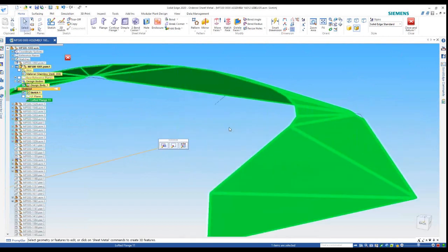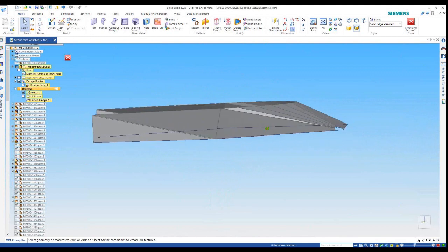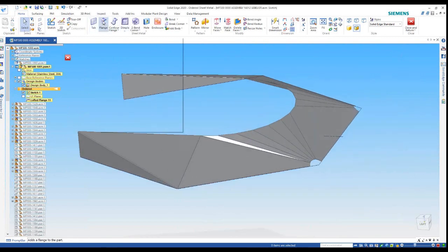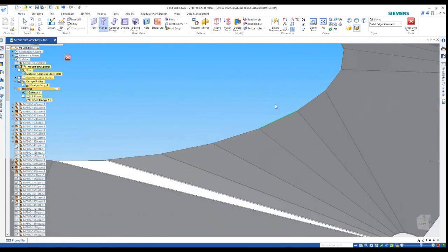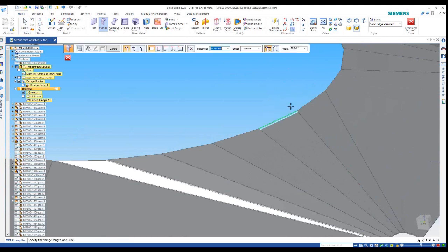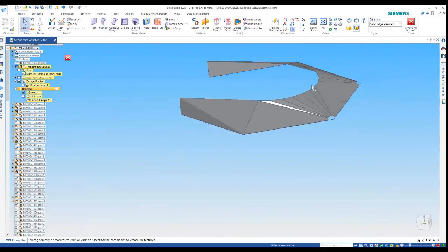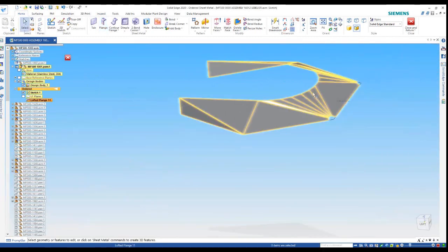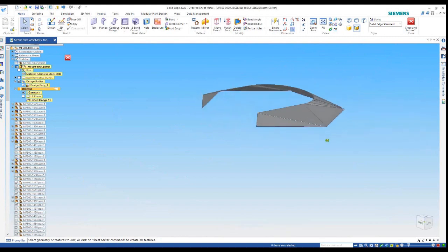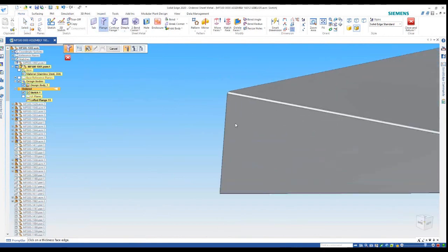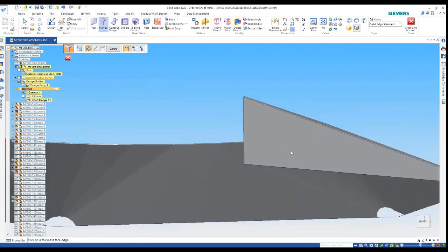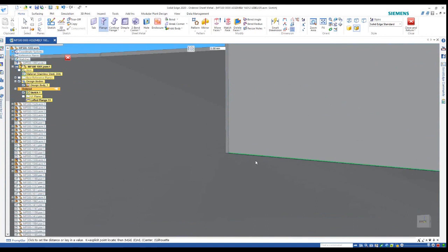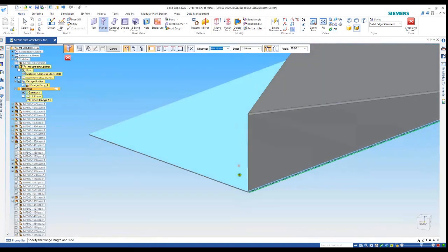You can see that it generates your actual lofted flange. Now you'll notice, I don't actually want to put a flange on here, but you'll notice I can put a flange on any of these edges now. If I was using the old bend triangulation method, just the bend lines, then I would not have been able to put that flange. So we'll continue on. I'll put a flange on the bottom here first. Might want to come in, for example, 35 mil.